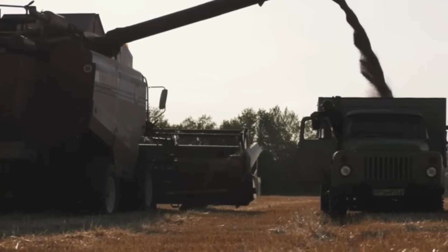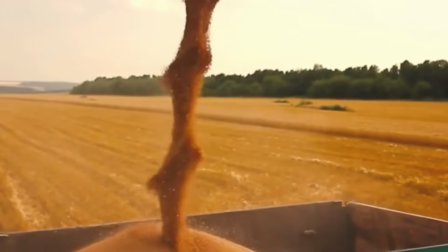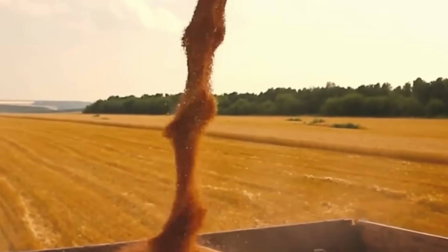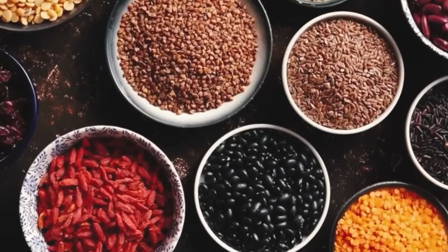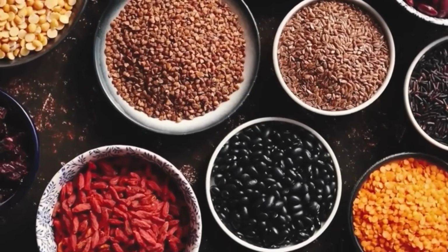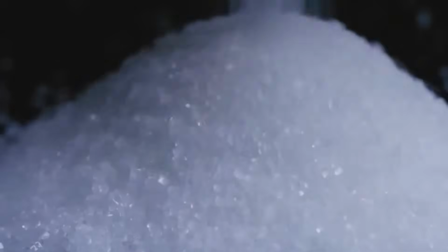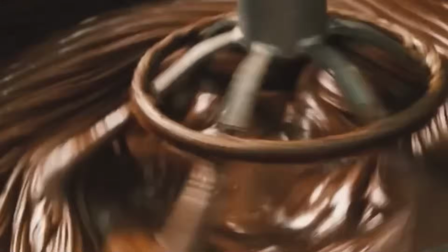Product testing occurs hourly. Samples are collected from each production lane and evaluated for weight, length, height, filling content, shell texture, seal strength, and packaging tightness. Sensory analysis includes bite resistance, shell-to-filling ratio, and flavor consistency. Non-conforming samples trigger root cause investigations documented in deviation reports.